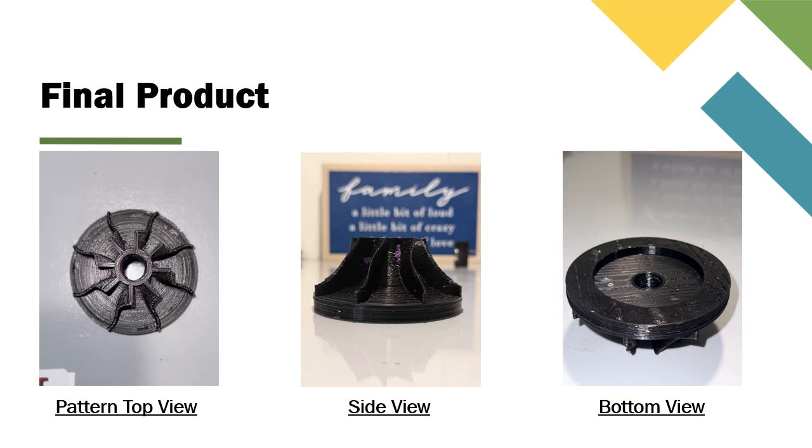This is Andres Gonzalez. So here's the final product we got from our casting. If you look at the bottom view, you'll see a white plastic ring. We glued that to the wax pattern to help us pull it out of the kinetic sand mold. That ring really helped avoid damaging the shape, but even with that, the wax stuck onto the sand and a few fins broke off when removing it.